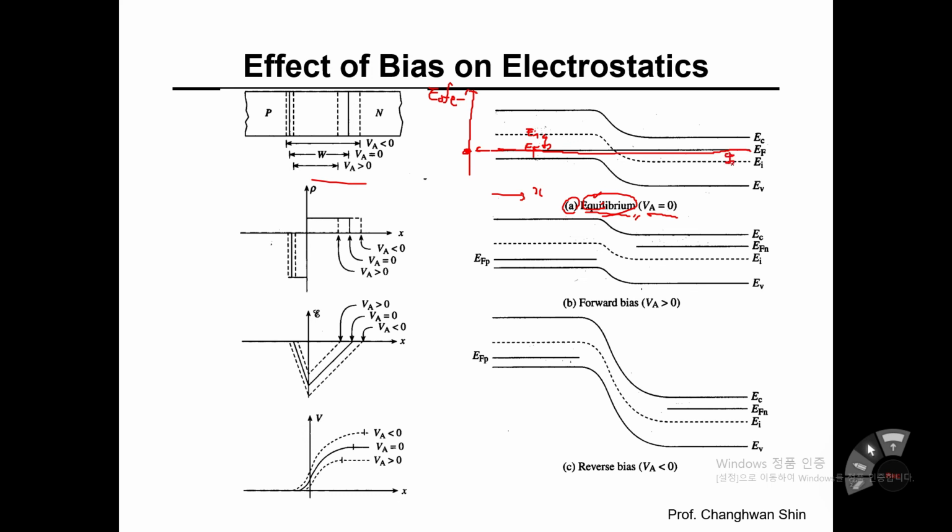And here EF minus EI, this energy difference is well matched to the doping concentration on the N side. And here the band bending has happened, right? We can use a second order polynomial equation to describe how much band bending has happened across the PN diode. And here you can see the two different curvatures, and this point is well matched to the physical contact between P side and N side. And as I have told you, the upside direction indicates a built-in electric field across the PN diode.